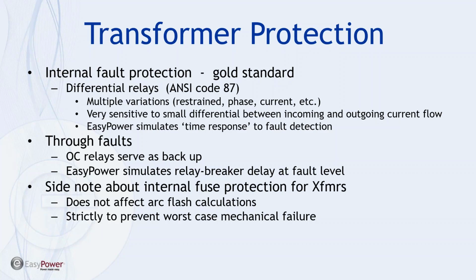The main advantage is that because they null out the normal or regular current in the system, they can be set to respond to very small differentials between the incoming and outgoing of the protection zone. And as such, it's difficult to model the current aspect of the protection. So in EasyPower, we simulate the time response for a bus that's protected by the relay breaker combination. We'll show that as we get into setting those relays.